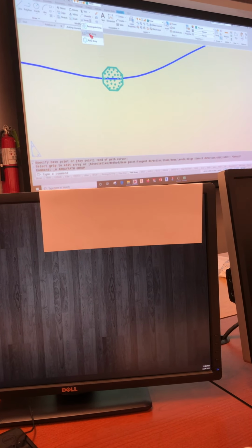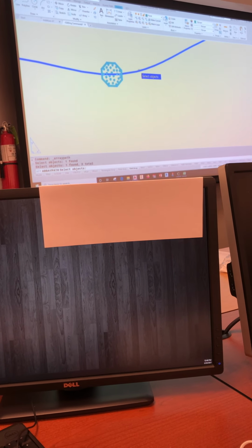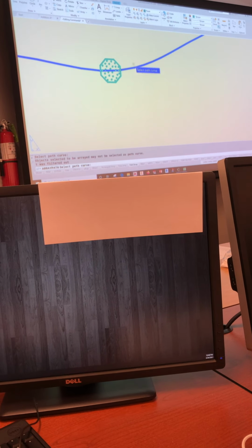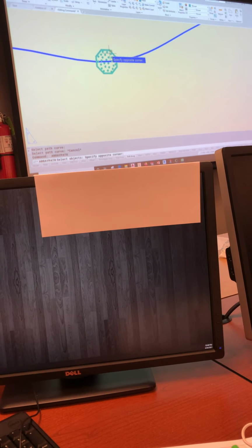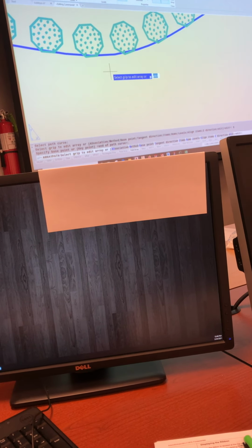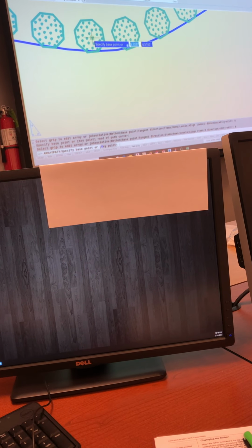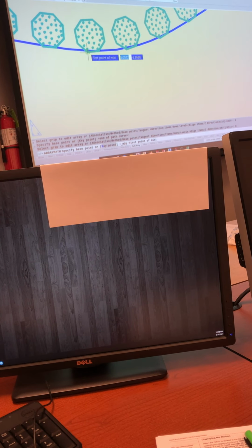If I do path, pick the object, pick the path. It didn't pick that. Now if I change my base point to another corner, for example, that corner will be touching the object. Base point, I'm picking the center. This time I'm going to be exact. I'm going to use midpoint between 2 points.